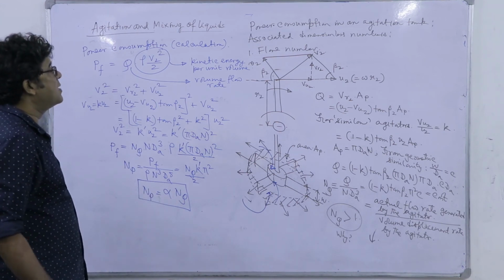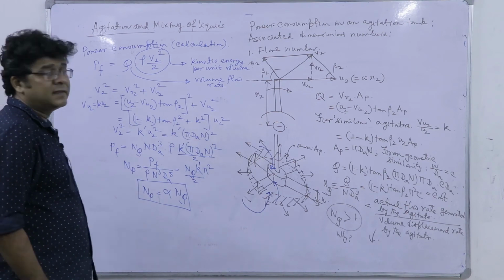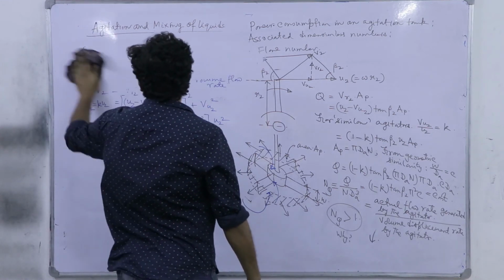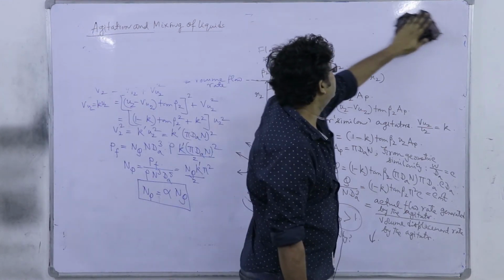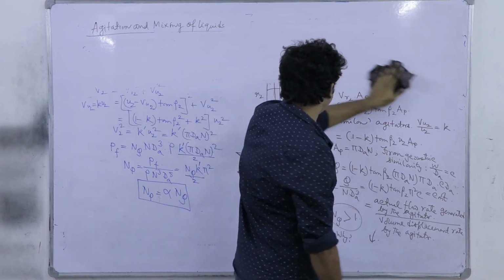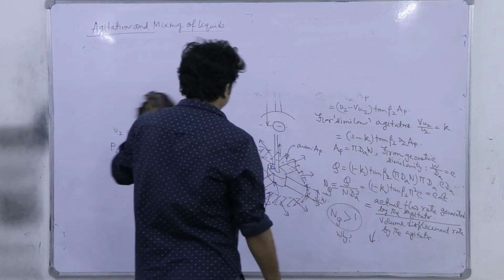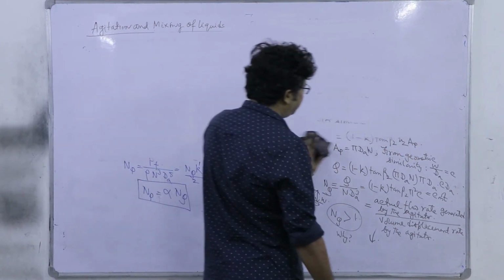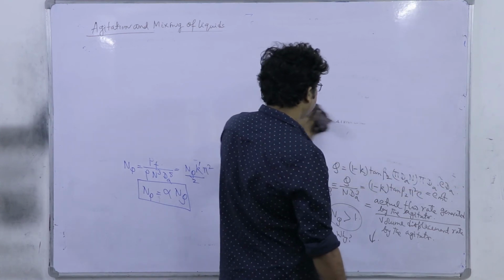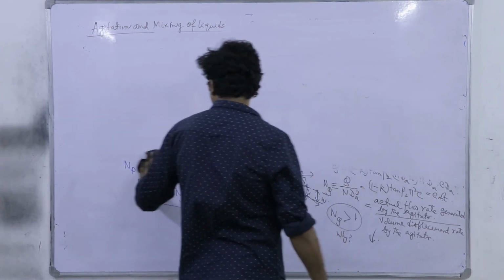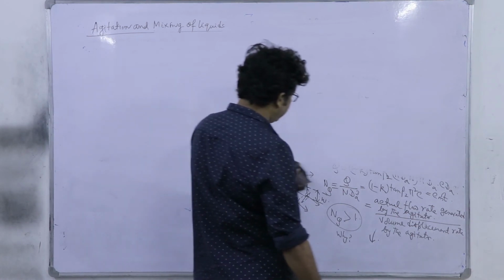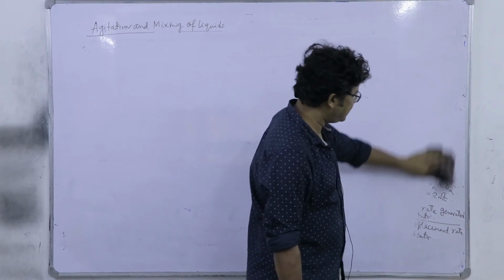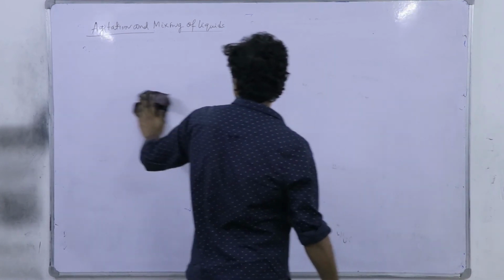So we have to go by a more basic approach of engineering, that's the dimensional analysis, right? So power we will try to relate dimensionally, specifically by using this Buckingham pi theorem and all, to the different appropriate parameters and variables of this system. These variables include the geometric ones and the rotational speed, then the density, viscosity, the diameter, etc., right. These are gross variables.